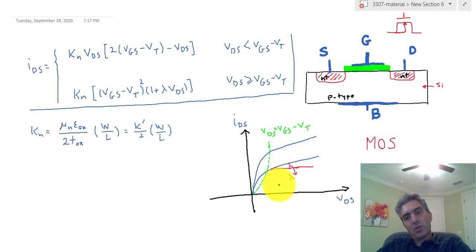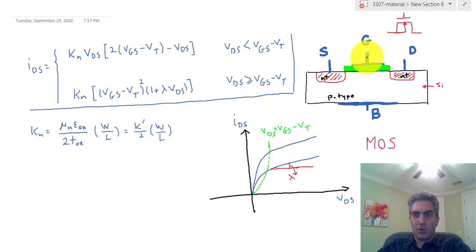But if I don't want to complicate it, I can put the voltage-current relationship for the drain and source in a 2D plot, and then draw the same plot for different values of gate-source voltage, or the voltage between gate and substrate. Since we connected the source to the body, the voltage between the gate and the semiconductor is the same as the voltage between gate and the source.